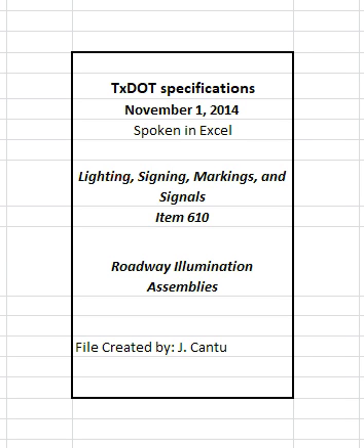Disconnect and remove conductors from abandoned circuits. Remove abandoned conduit and ducts to a point 6 inches below final grade. Unless otherwise shown on the plans, remove abandoned concrete foundations, including steel, to a point 2 feet below final grade. Backfill the hole with material that is equal in composition and density to the surrounding area. Replace surfacing material with similar material to an equivalent condition. Do not remove existing concrete bridge lighting brackets. Accept ownership of unsalvageable materials and dispose of in accordance with federal, state, and local regulations.